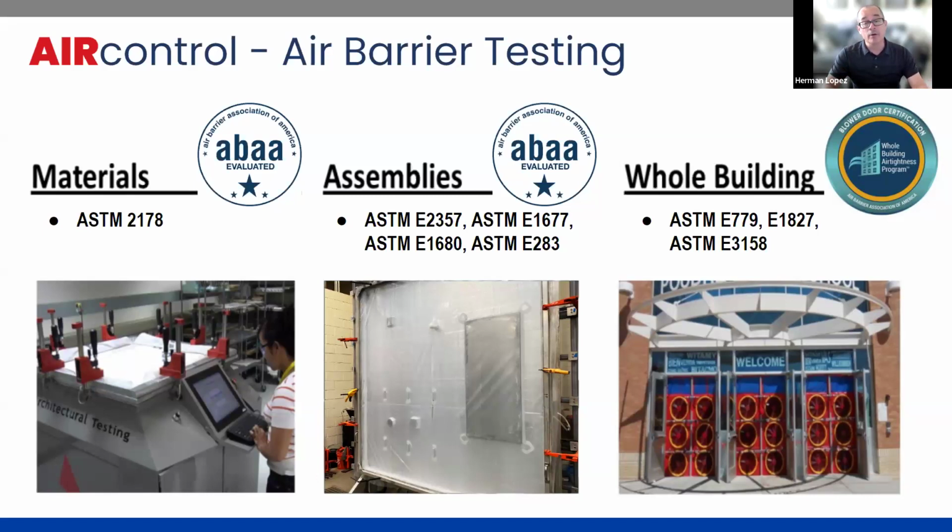We do quite a bit of it here in Colorado, and it came up quite a bit in New York, because I think we're starting to see, to your point, Ben, bigger and bigger pockets where whole building blower door testing is being requested either by code or even by owner developers. It's a test of the craftsmanship. And having been on a number of these projects, there's a lot of nervous people in the parking lot when these tests are being done, because you're really being graded by the people you've put on the project. Yeah, that's a great point.